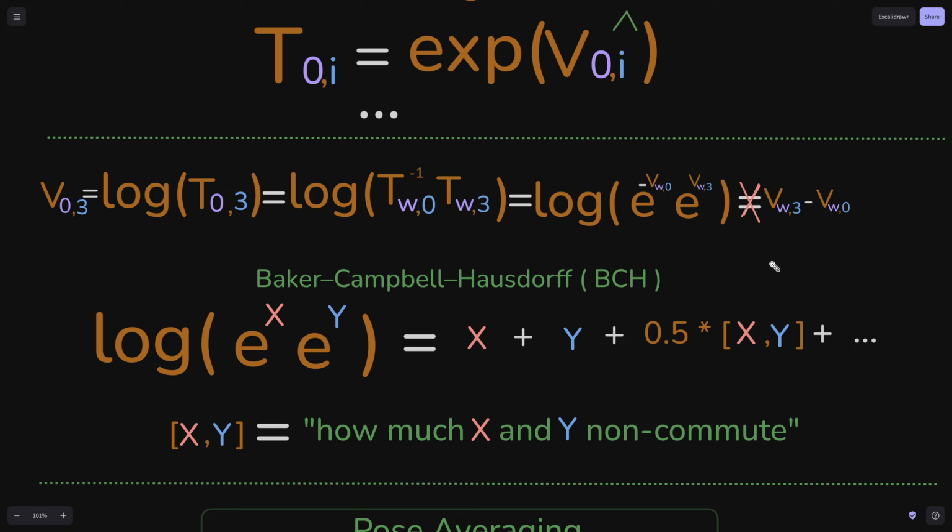But in general, when you have interesting Lie groups, like the SE3 that we are dealing with, which is non-commutative, this is not true, okay? But nonetheless, this is actually also an approximation, right? And we will see later on that, like you would do with a lot of robotics, you get the Jacobian and things along those lines, you get linear approximations and you iterate on those linear approximations, and this works out to do something that is nonlinear.